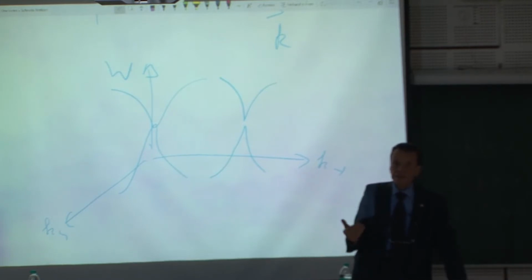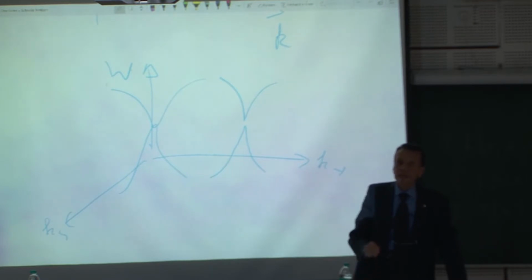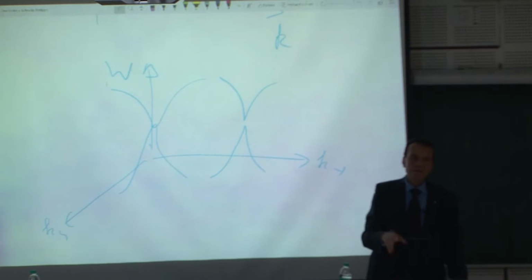If you now integrate graphene in a FET, field effect transistor, you can Google and look. You have plenty of publications. You can overcome the problem of, I would like to have high mobility. So I can now have a finite distance between the electrodes, between, say, source and drain in a field effect transistor, and nevertheless I have high mobility charge carriers, so that the transit time is really very, very low. And I can have now a bi-transistor. But again, the main problem is the efficiency.